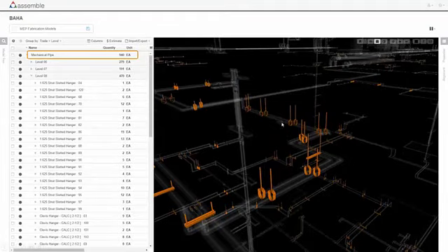And so now here we can actually see that I've just created a very quick view isolating the hangers on these 3 floors, and I can see how many and what kind they are, and do they pertain to that RFI or not, and I can continue to filter it down until I get the information that I need. And maybe it's how many are affected. If it's potentially a back-ordered item or a long lead item, you can actually drill into these things and very quickly understand the impact on your project or the data that you need to respond to an RFI in some situations.